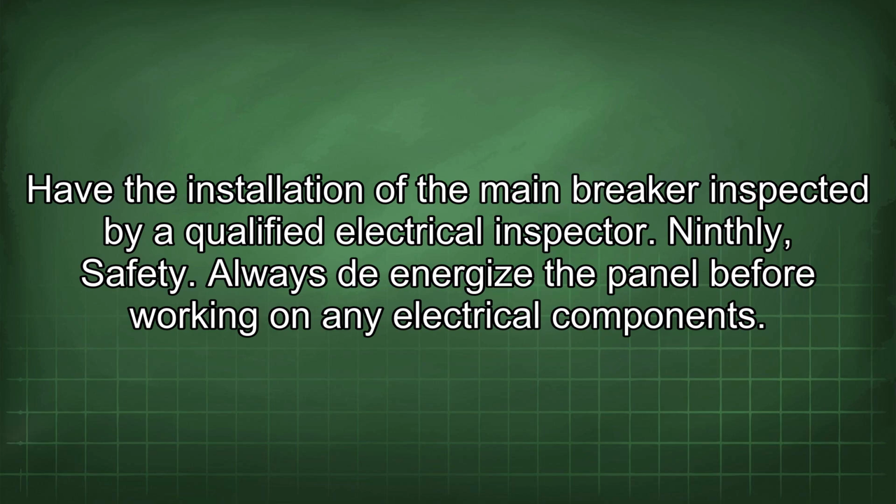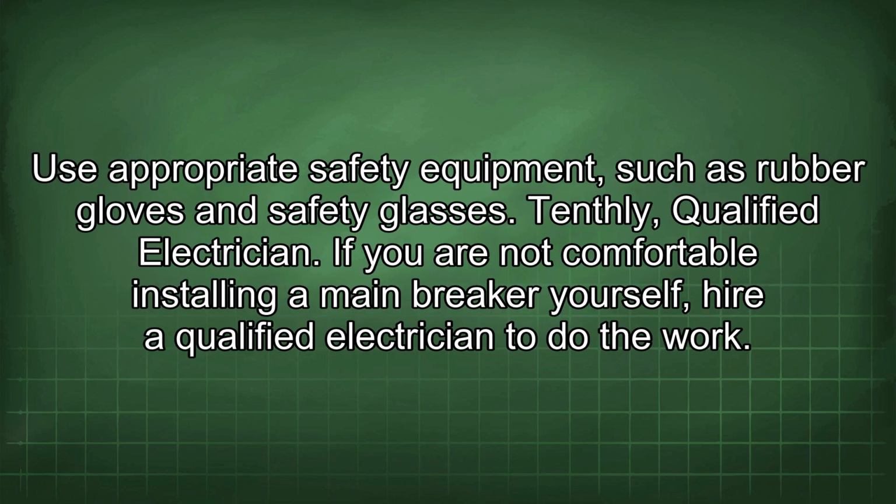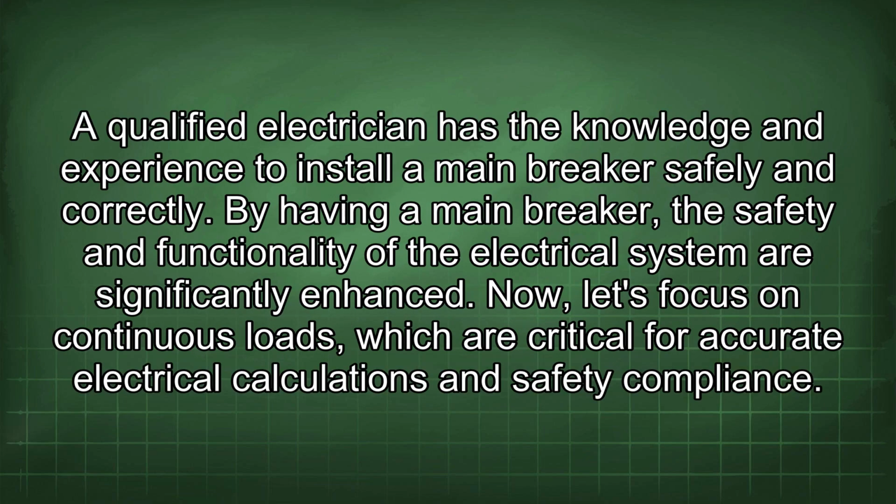Ninthly, safety. Always de-energize the panel before working on any electrical components. Use appropriate safety equipment, such as rubber gloves and safety glasses. Tenthly, qualified electrician. If you are not comfortable installing a main breaker yourself, hire a qualified electrician to do the work. A qualified electrician has the knowledge and experience to install a main breaker safely and correctly. By having a main breaker, the safety and functionality of the electrical system are significantly enhanced.